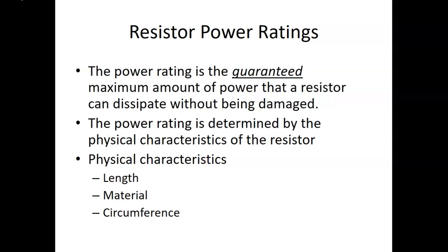But it's all about the wattage rating that they're looking for with these, not so much the resistance rating. Some of those resistors don't have a resistance more than about 5 ohms, but their wattage rating can be 500 watts. That's how much power they're putting out. But the size of it is also looking at how much current draw is it using. Because some of these can be hooked up to quite a bit of voltage, quite a bit of current, and if you don't have something that's got enough power rating to it, you're going to still blow it. So just kind of keep that in mind.